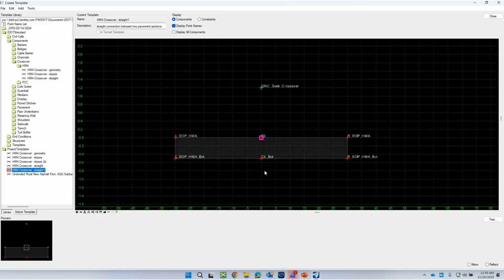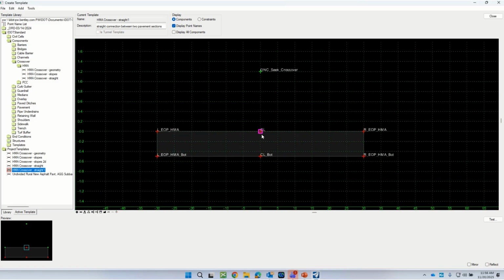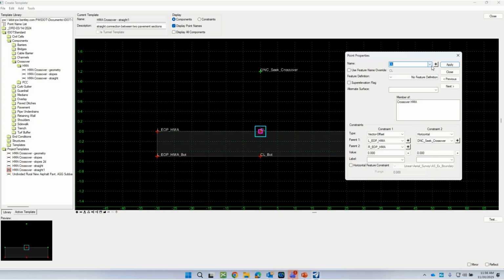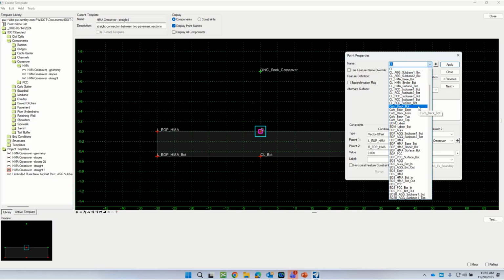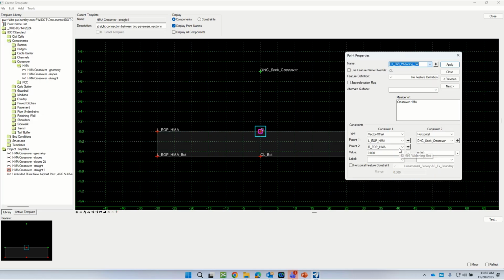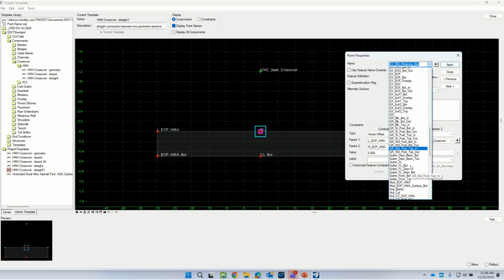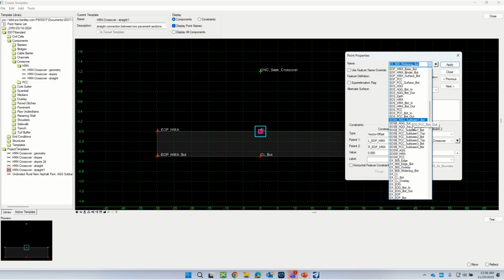And okay. So let's go ahead and get started. The user mentioned they want the slopes to be 2%, which works. Okay, there's no feature definition set for some reason. So let's go ahead and we'll select, I get anything here, existing center line, just to get something so it gives us a feature definition of some sort.